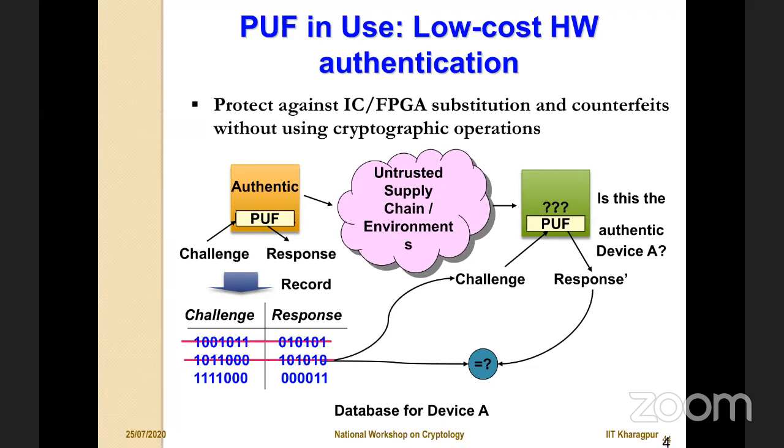Now, why it's called a strong PUF is because since the adversary is seeing the challenge and also the response, the adversary should not be able to predict the challenge or the response of a challenge which he is not seeing. To break this guarantee, what the adversary can do is try to develop a machine learning model for the PUF. This is what I meant when I said that the PUF has to be model-building resistant.